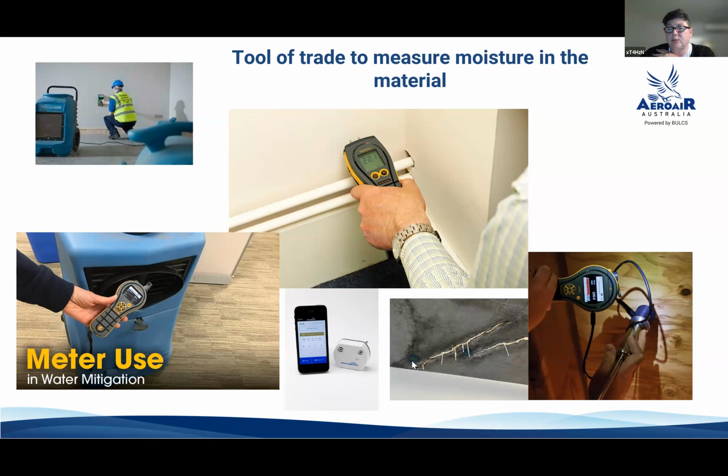So the only way to do it was to put a data logger there. We looked at when the rain came through, how fast it penetrated. By looking at how fast the humidity rose, we could then determine if it could have been what either one of us suspected. And then the last thing, I think the next one is also the pin reading, which we talked about.